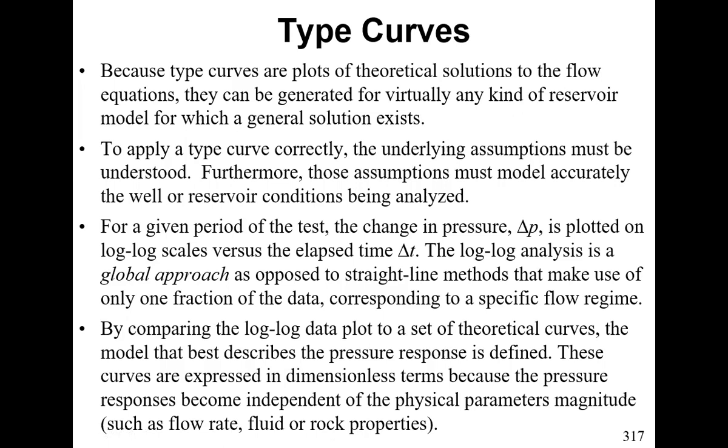By comparing the log-log data plot to a set of theoretical curves, the model that best describes the pressure response is defined. And when we talk about model, we're talking about the analytical solution that best represents the well reservoir system that we're working with. These curves are expressed in dimensionless terms, and as I mentioned earlier, the pressure response becomes independent of the magnitude of the physical parameters.